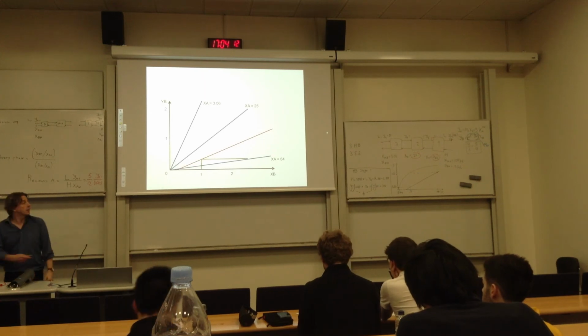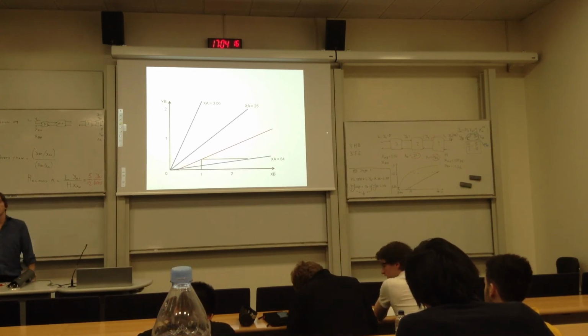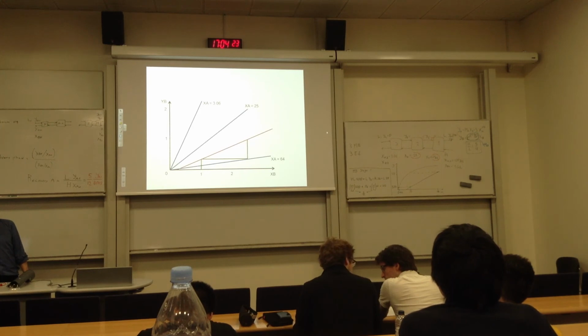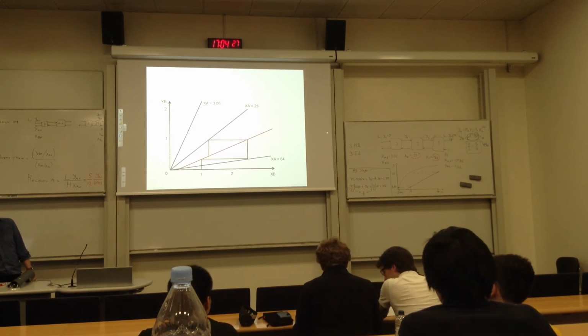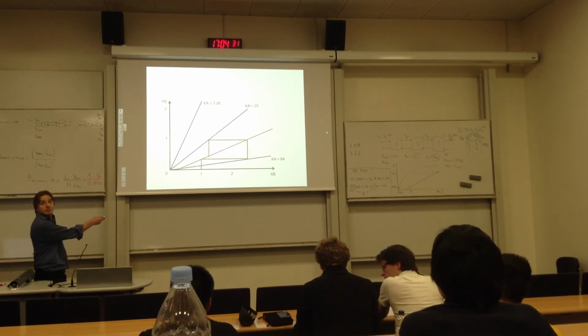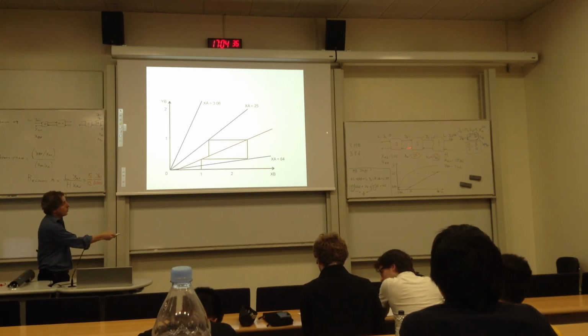So what happens next? How do you find YB2? Vertically and going where? Up to the red line, the operating line. And then, do you agree with me that this is the point corresponding to the second stage? This is the equilibrium. And once you know, so this relates these two, and then you can find Y3 by coming down vertically to this point.